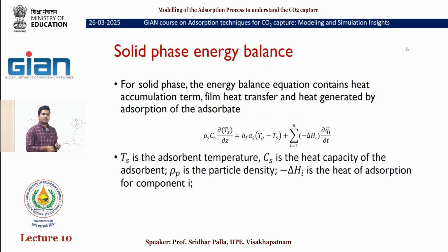So this is the heat of adsorption, how much heat is released during the adsorption. It involves dou q by dou t, again going back to our kinetic model. Whatever information we obtained from the species balance would couple this energy balance with the mass balance equation.